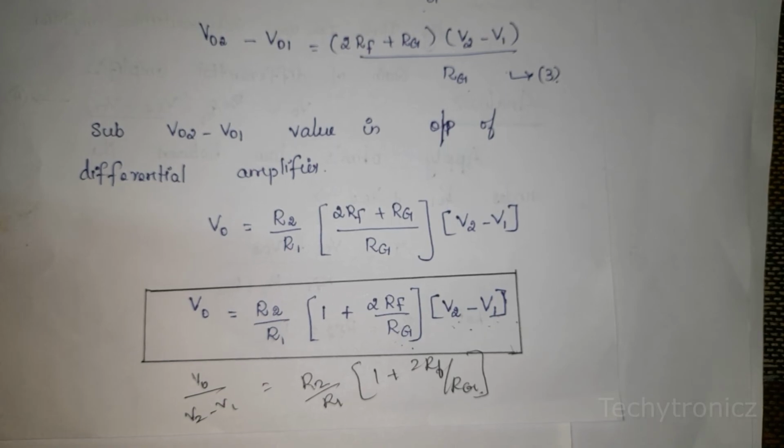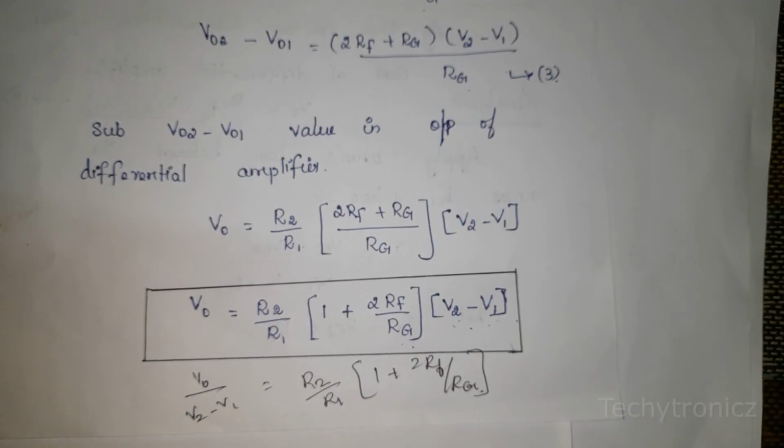The output of the transducer, when transmitted over long transmission lines, has large common mode noise voltages. The instrumentation amplifier must amplify only the differential input, completely rejecting the common mode input component. Thus, it must ideally have infinite CMRR.